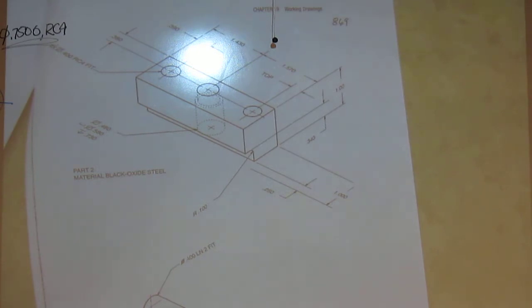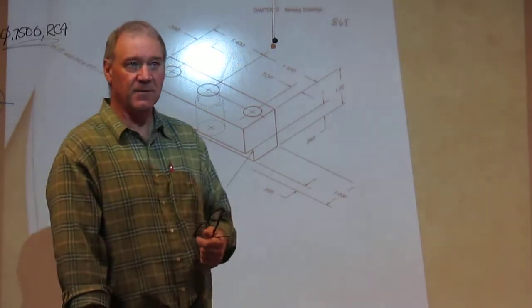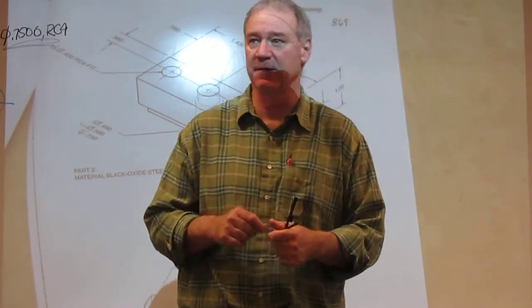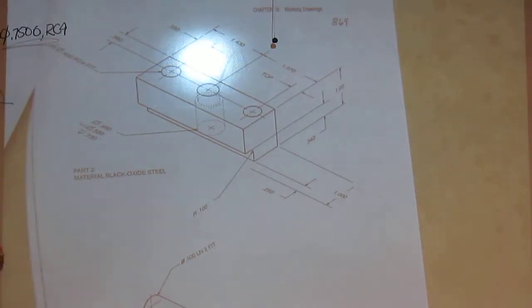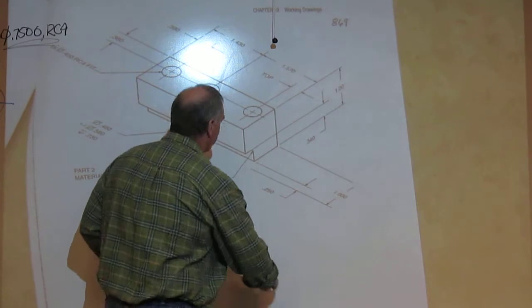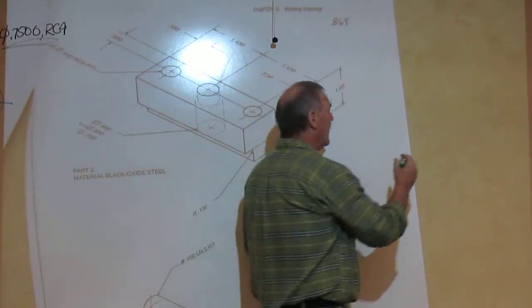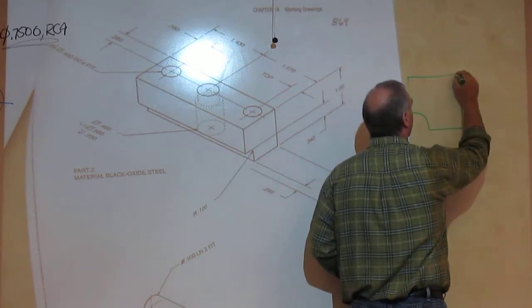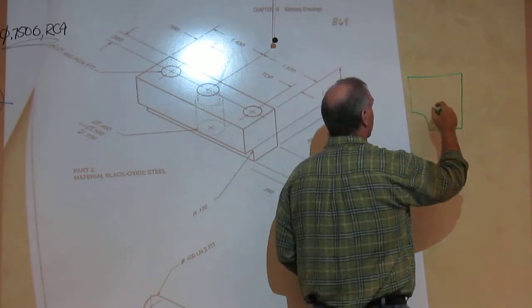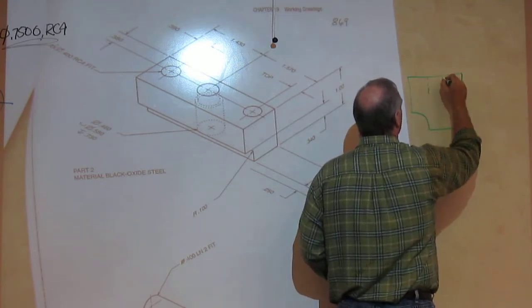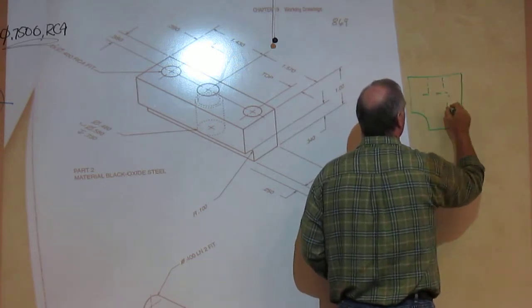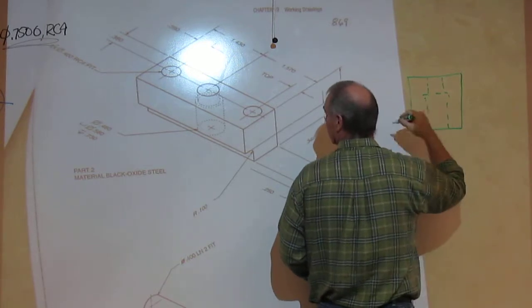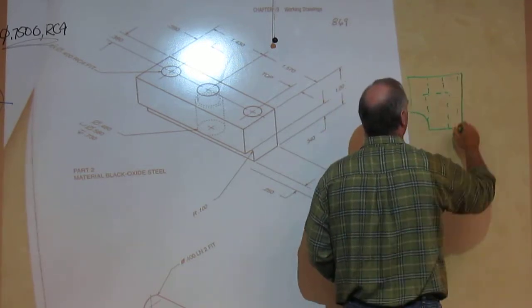Okay. When we do a finished surface, how do we do it? I would like you to use the general surface finishing symbol for this. It's back in chapter 10. And in essence, you apply it everywhere you see the edge view. So as an example, let's say I'm getting this guy and I'm drawing it. My right side view is going to look something like this. And then I've got some holes that come through. This guy's counterbore where the spring comes in, whatever it does. Then I've got these 2 out here.